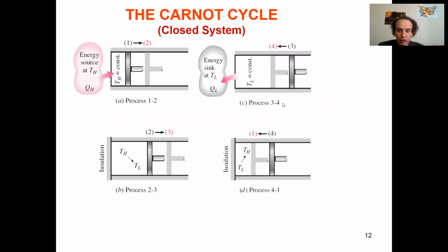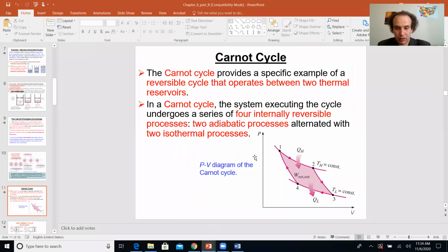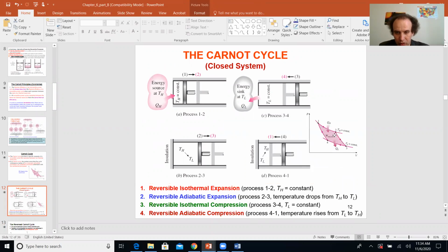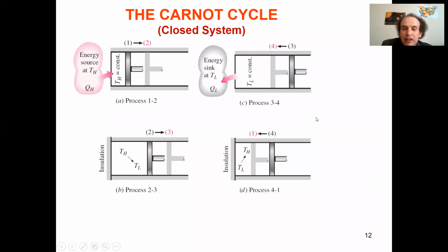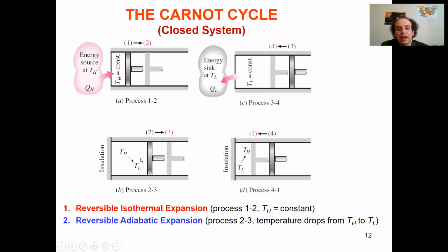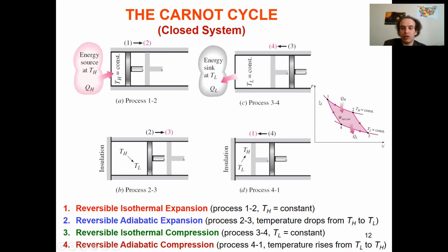How it goes again, you may take a look here if you want. I can actually show it on a small scale here. Yes, it will be nice to see. So basically, that's what we have. What do we have in such a Carnot cycle? First, we have heat addition to the system, right? Reversible isothermal expansion. Heat goes in, the piston goes like this. Then you have reversible adiabatic expansion here. Then reversible isothermal compression. And eventually reversible adiabatic compression. Do you understand?